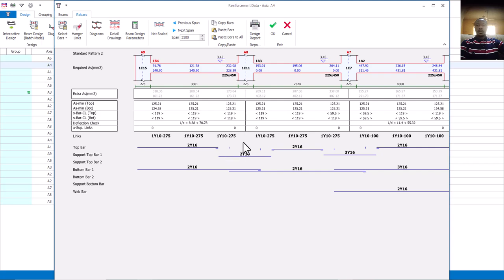So now you know that at site we cannot be cutting iron like this, isn't it? So it must go straight, and our length of reinforcement is a 12 meter length. Until the entire length has finished, and you still have more space, we are going to have an overlapping within the column, isn't it? So that's that. All right.